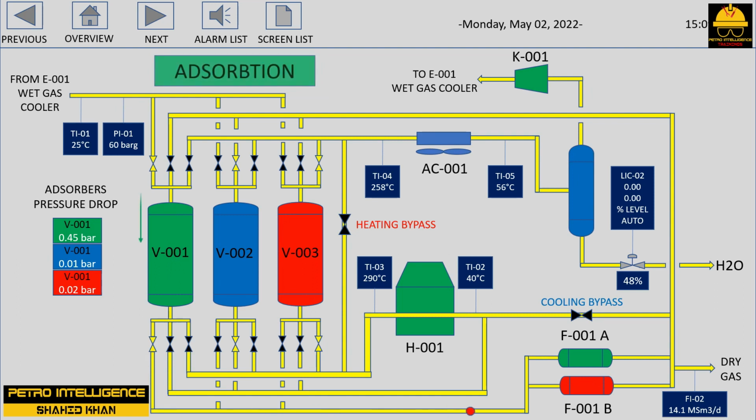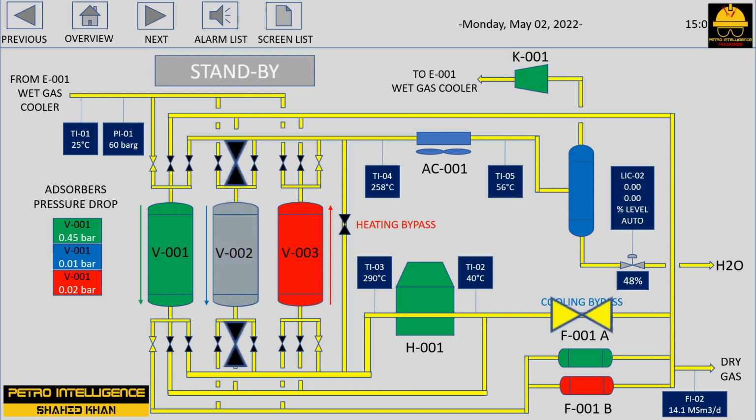1. First, after the bed is bypassed, the process stream is displaced from the bed by draining it or displacing it with another chemical. 2. The bed is sometimes washed or flushed to remove any remaining process chemicals as well as solids, dirt, or trash. 3. The regenerating step itself involves soaking the ion exchange resins or purging the molecular sieves. 4. Finally, after regeneration, the bed must be returned to service. This step involves clearing the bed of the regenerative chemicals and preparing it for normal operations.